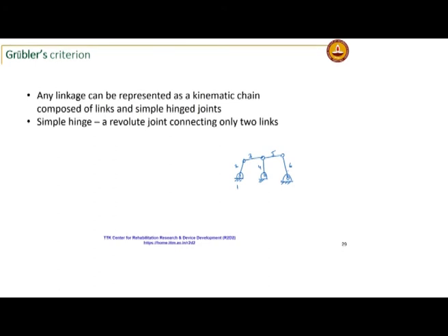You will find that it has mobility equal to 1. Here I have what is known as a multiple joint. I have 3 links coming together at this joint.